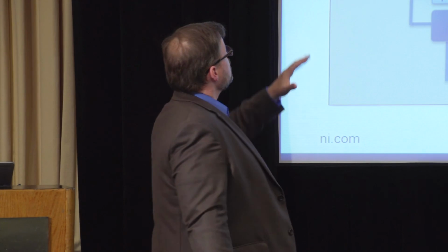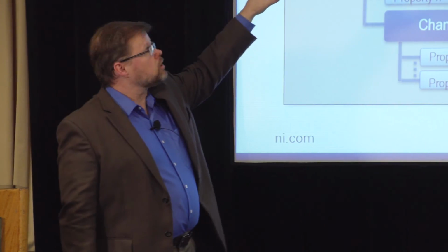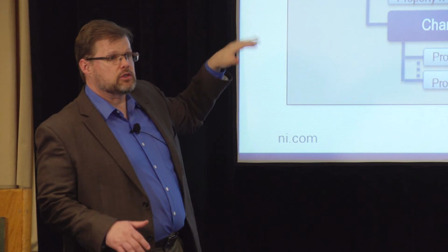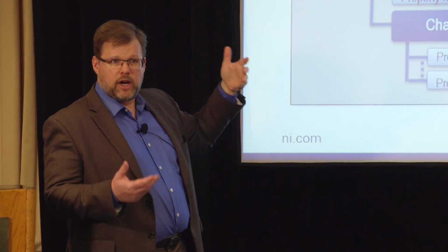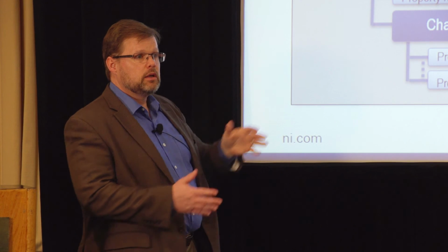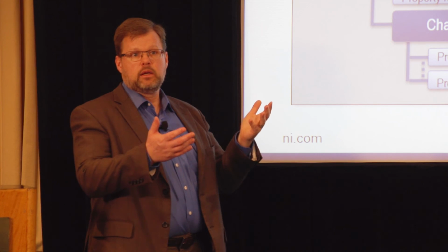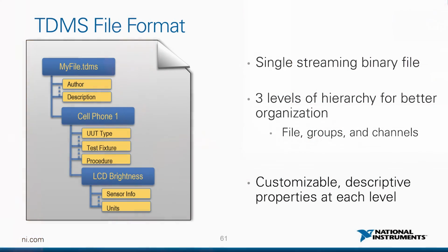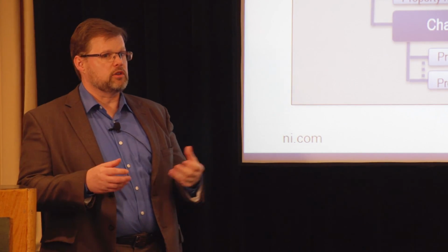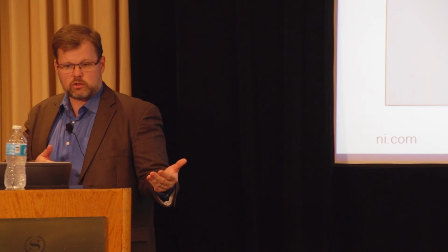Okay, so there's again, an open standard called TDMS, which is a file format that's sort of self-documenting file format that uses an XML header and then binary data underneath to move around large amounts of waveform data. Because most of the other standards are about, you know, floating point values, scalar values, or collections of scalar values, not waveforms that are associated with single channel. Sort of a different concept. Here's an example of it mapped to a cell phone test. This hierarchy.